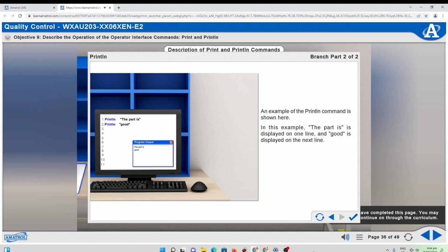Industrial robots are often used to load and unload inspection devices for measurement of features, such as length or diameter. Some robots, however, actually perform the measurement operation. Robots with a built-in measurement capability have the advantage of conserving movement, thereby increasing speed. Their primary disadvantage is that they cannot achieve the degree of accuracy provided by standalone measurement devices.